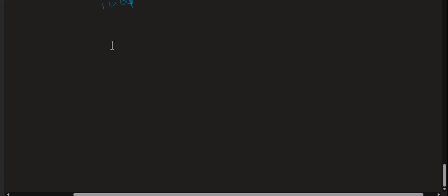You probably said this. The Johnson is always going to be 8 states or less; 8 is the maximum. And for a ring, n is the number of bits. So 2n is the maximum for Johnson, and for a ring, n is the max.